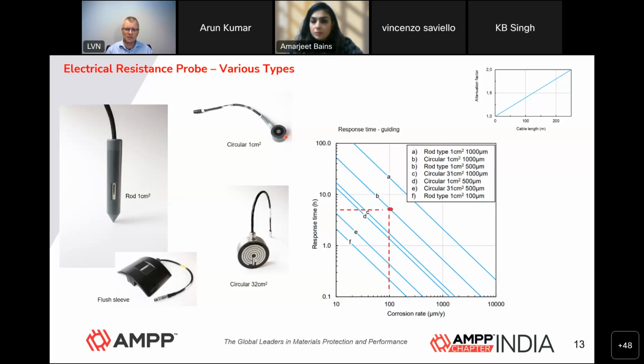When it's buried, it's buried. But of course you should measure on that coupon. And you say inevitably that there can be some pitting generated on that coupon. If you operate your system as I have tried to illustrate, in a good way, there shouldn't be any pitting or corrosion on that coupon.